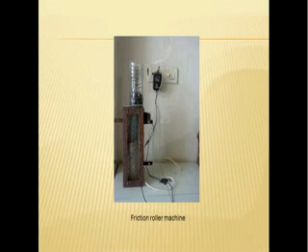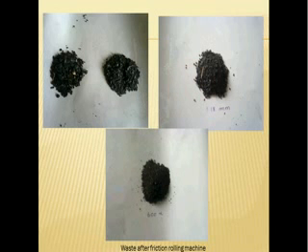So this was the first preliminary machine which was fabricated by us. It has a hopper, and it contains a motor with 2 friction plates, in which the waste comes and is ground between the 2 plates, so it breaks and also develops a rough luster. In these photographs we can see the difference between the 2 wastes. The first was the waste, and the second we processed, so it became rough, and the particles were also divided into smaller particles.